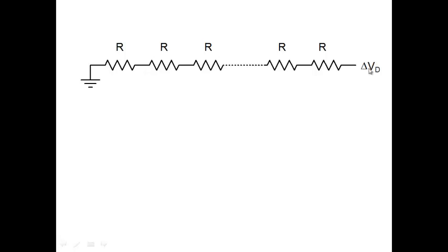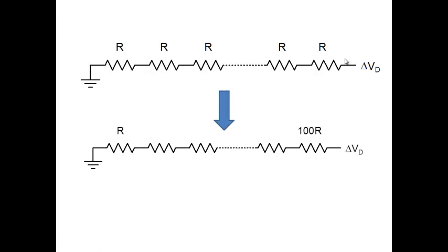And if you apply and increase the voltage, the current of course increases throughout the channel here. But then the moment you get close to saturation or close to pinch off, the resistance in the channel is reasonably small. But as you get close to the drain, you get resistance which is very large, very small inversion charge density. So now if you apply an incremental voltage here, everything will get dropped here, hardly anything will get dropped here. Right?